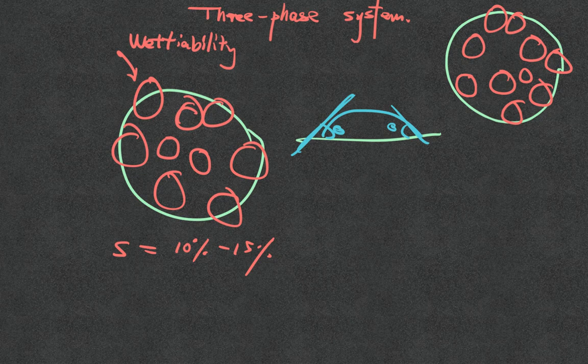In general, for most soil, granite, quartz, that doesn't actually absorb water, the contact angle will obviously be less than 45 degrees, and it would form something called a liquid bridge, which means that the water would act like this. Okay, so they will form a little bit of a bridge.